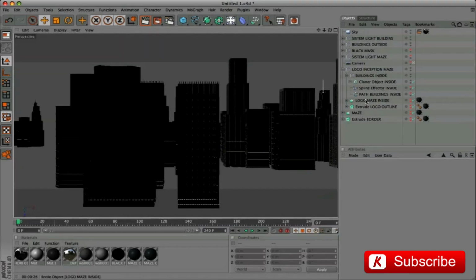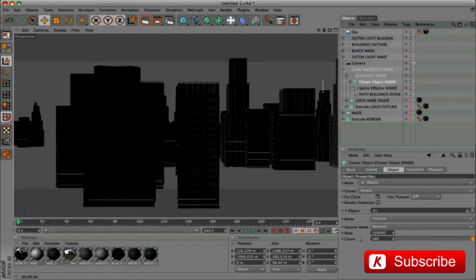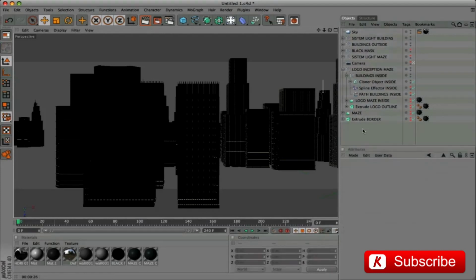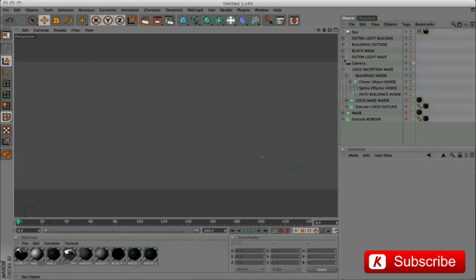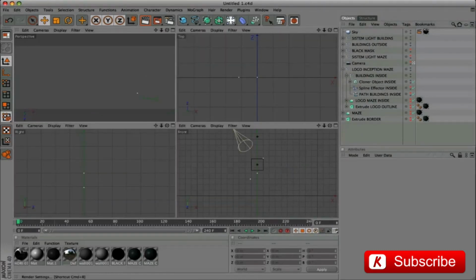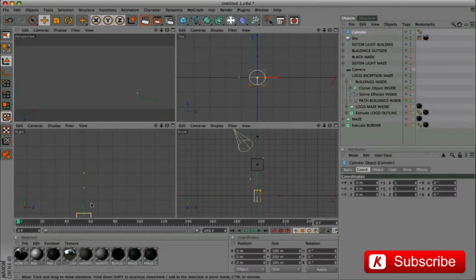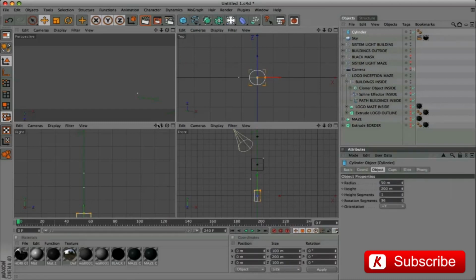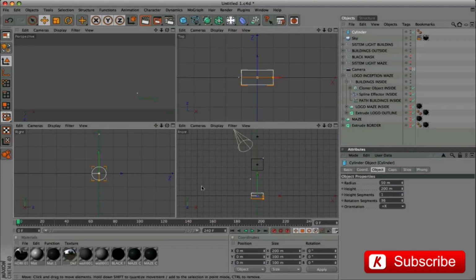Now, in our stage, add 2 cylinders with neon effect, to reflect light on skyscraper's windows. Add the first cylinder, oriented along x-axis. And change the size: radius 8, and height 19-20 meters.